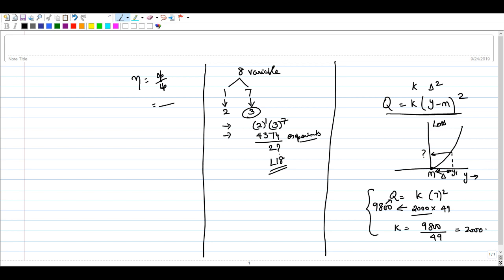Yeah, so Varshil Shah has this question on what is the difference between FM and FR. FM is the maximum feed rate and FR is the required feed rate. This FM, maximum feed rate, is more like a specification for the machine. It says that the machine can only feed at this rate. So let's say the feed rate is 10 per minute.